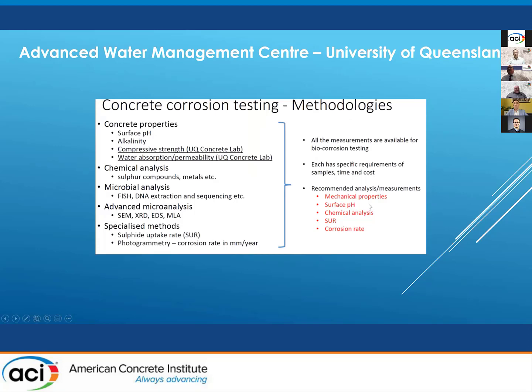One of the questions was asked about the influence of different kinds of cementitious systems on stage 1 and 2. So looking at that initial pH drop can help in that regard. And indeed, calcium aluminate cement is basically focusing on retaining, because of its buffer potential, it's effectively elevating the pH and preventing the pH from dropping too much below 3 or 4.